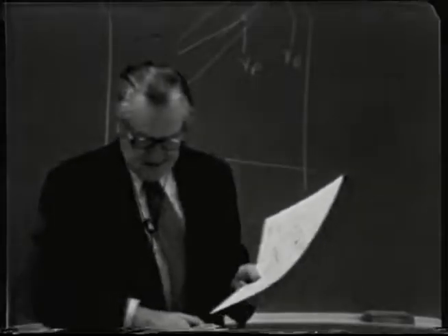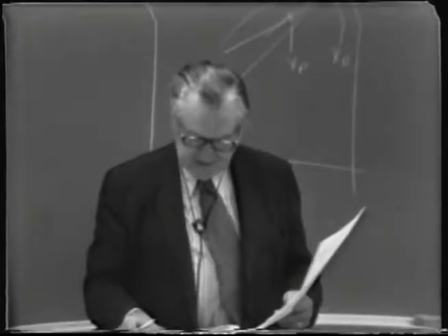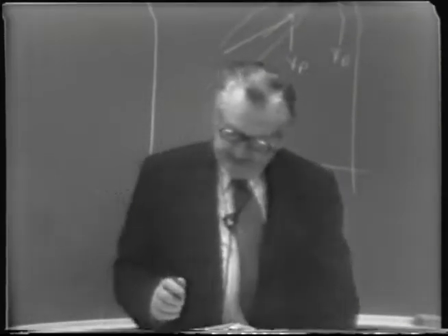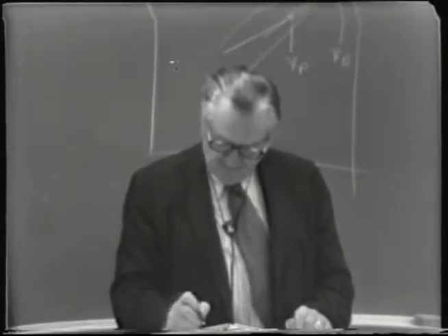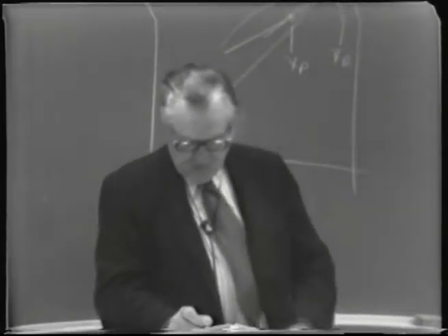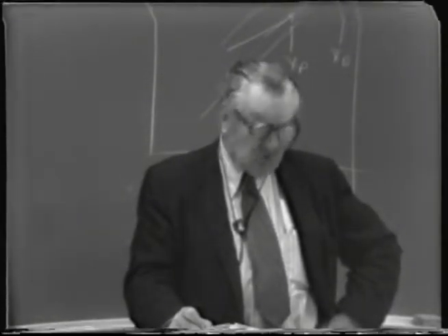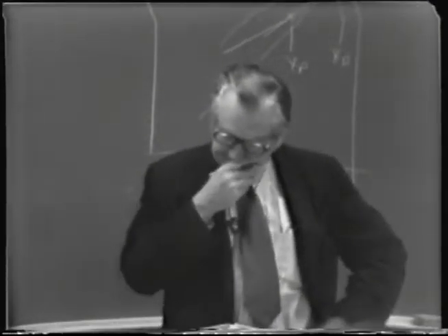So, reading off graphically that slope by scaling off of the scale, I determined that the reflux ratio, L sub P over V, or the slope of that line, is about 0.650 to 1.